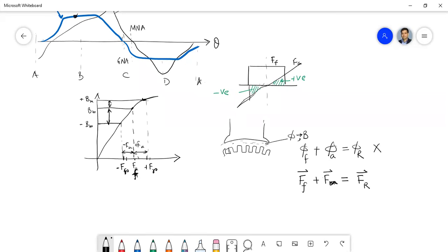Is that clear? Okay, then you've said that the eddy current and hysteresis loss increases due to the increase in flux density. So that is contradicting what you've just said. Under the effect of armature reaction, you said increase in iron loss. So you've said that the eddy current loss and hysteresis loss increase due to increase in flux density. No, no, maximum. So that is the maximum flux density. That is different.